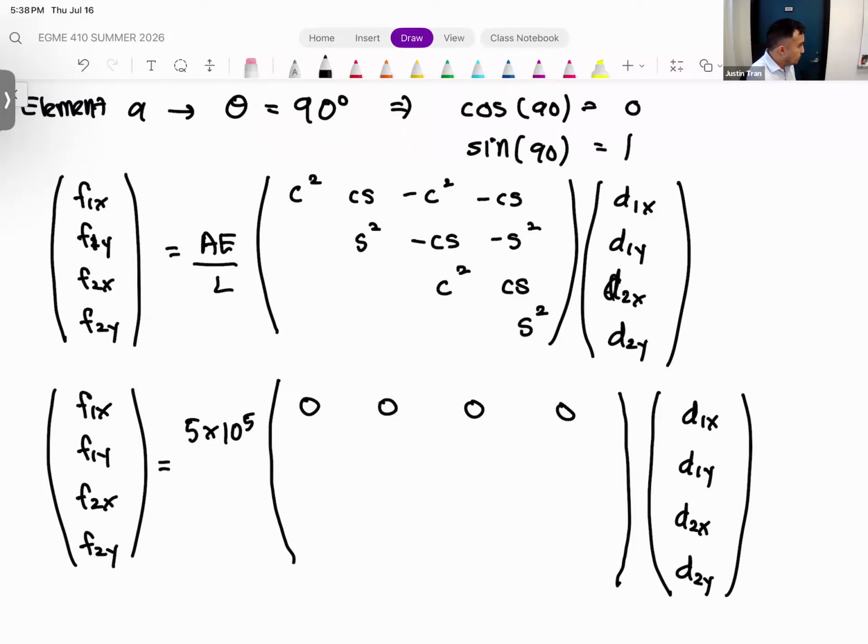All right. So before we move on to the second row, we're going to take advantage of the symmetry that we have in this matrix, right? So remember, the reason I only define the upper right portion is that it's symmetric with the bottom part, right? And so one way to take advantage of this is that every time you write a row in the element stiffness matrix, you can write that exact same row into the column, okay? So you're basically going to take that row and transpose it down.